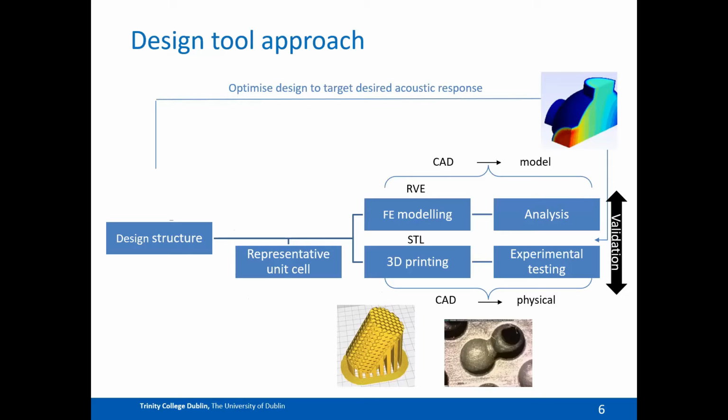The approach used to assess the performance of the design is presented here. As part of the periodic acoustic structure that is designed, there's a representative unit cell. On one hand, you try to numerically predict the acoustic behavior in microacoustic systems. We know that there are important dissipative effects that need to be included, so this detailed description is required when you analyze such behavior.